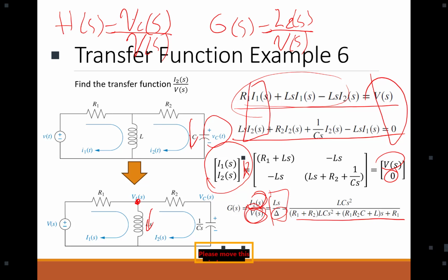It's not just the current. By the current, you know if you're in a steady state and using the capacitor in a proper range. By analyzing the voltage across the capacitor, you find whether what you're doing with the circuit keeps the capacitor in the safe interval regarding the voltage. This is one reason why you need to analyze both the current and voltage of the capacitor, but that's not for this question.